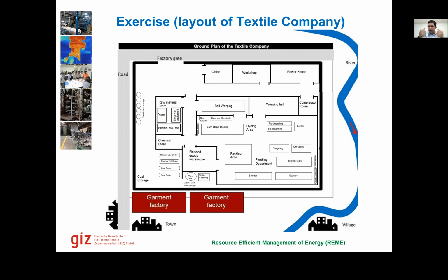It is not a very tight rope. This rope then goes to the rope dyeing process. Because this is a denim factory, we do not dye the fabric, we dye the yarn. The yarn is fed to this machine in the form of multiple ropes. They go in rope form like this, and the whole rope is dyed and comes out. When it dries, it goes to the weaving hall.